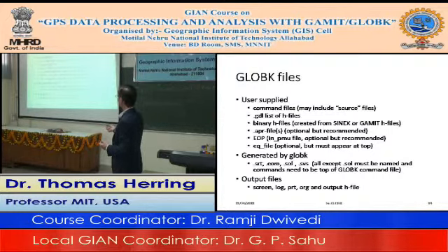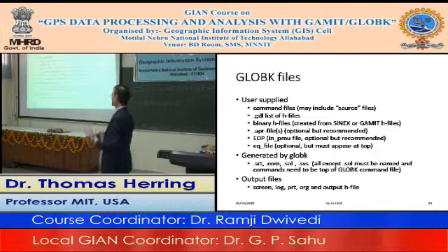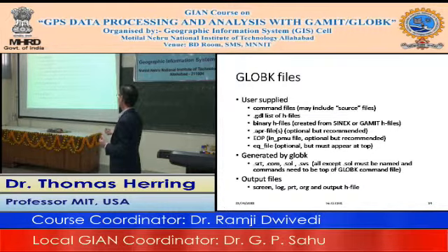The a priori coordinate files are optional, but we recommend that you use them, particularly if you're doing reference frame realization. If you do not give them, GLOBK will use what it infers from the input H files, which often is okay, but sometimes can be a little uncertain. There are Earth orientation files. Again, optional, but if you're estimating Earth orientation parameters, we recommend that you have them there. Again, not particularly critical.